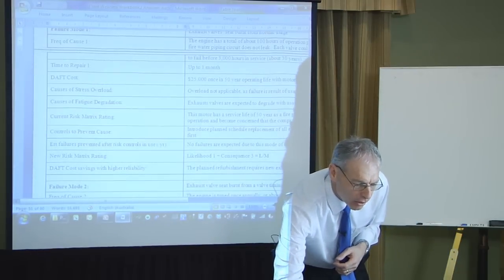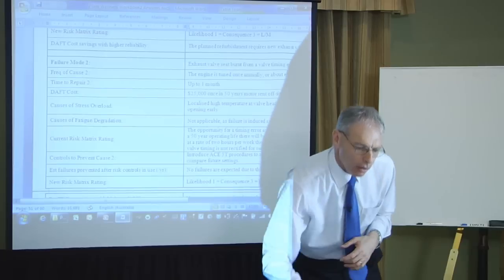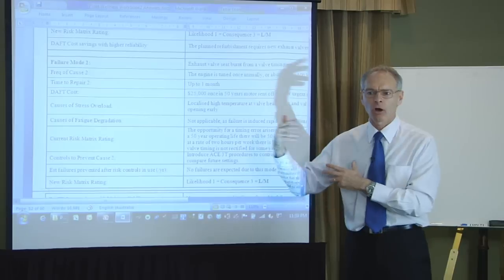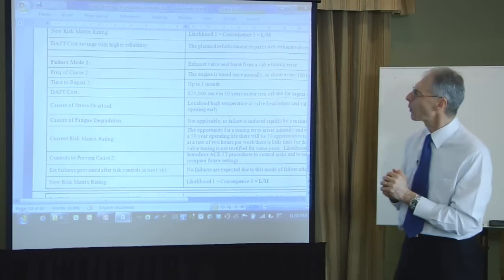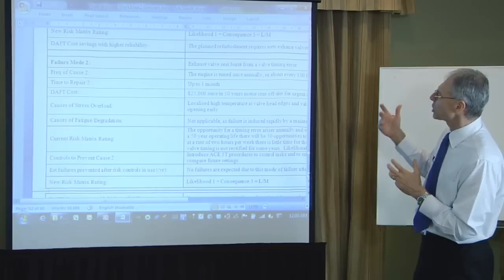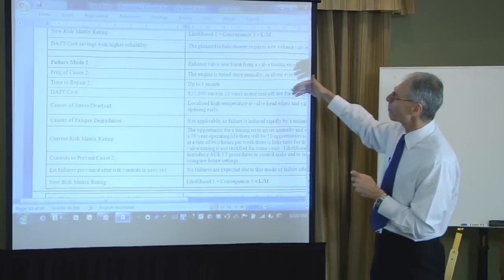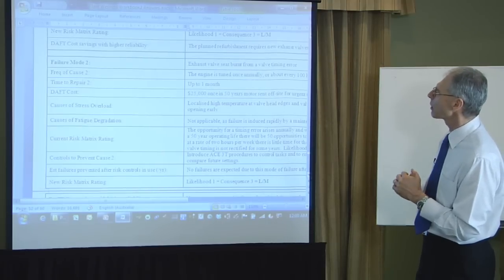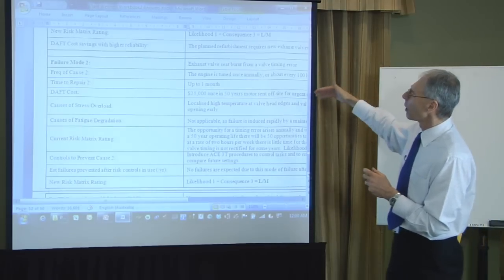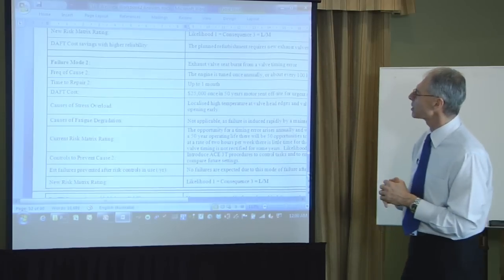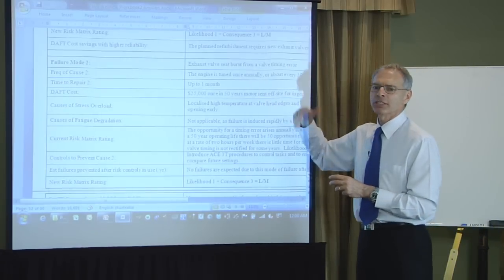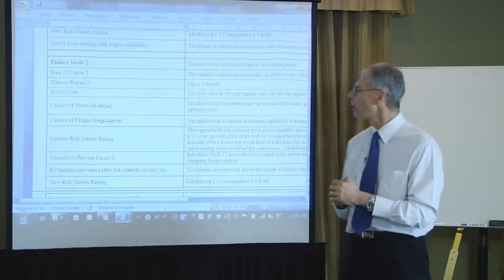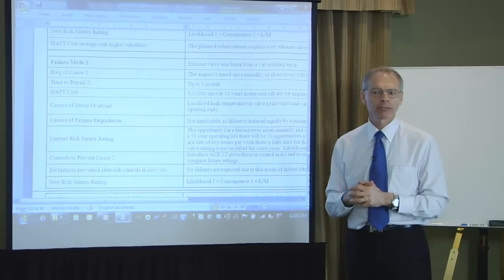What other failures can occur? We can have timing errors. That valve can be burnt from timing errors of the ignition sequence in that engine. So what's the chance of that happening? If it does happen and we destroy the valve from mistiming, again, we're down for a month. The cost will be the rebuild of that motor, $25,000. We expect that to happen possibly once in 50 years. This terminal will have a life, typically 50 years is a reasonable life for a fuel terminal. The chance is there that this might happen once.